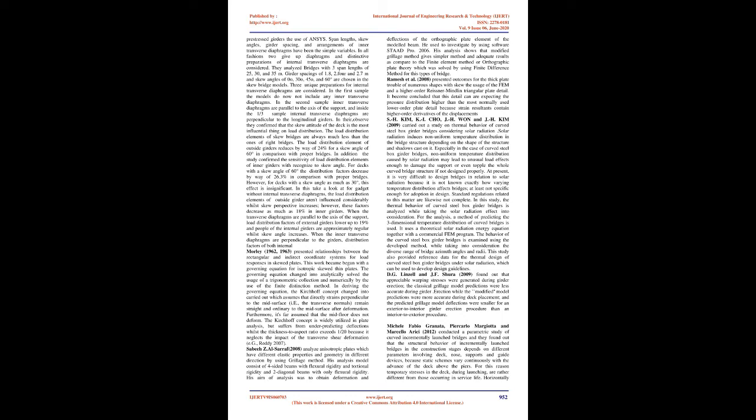The analyses showed that the bending moment in girders of a curved bridge can be about 23.5% higher compared with moments in girders of a straight bridge of similar span and design configuration. As a result of the curved geometry of the bridge, a torsional moment is developed in the girders. The magnitude of this moment was found to be about 10.3% of the maximum bending moment of a comparable straight bridge. The vertical deflection of a curved bridge is about 80% higher than the deflection of a straight bridge.